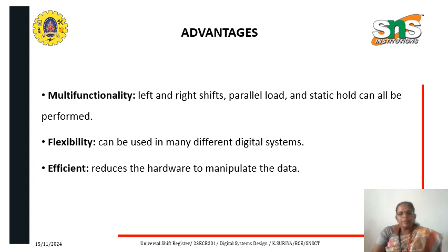Next, we'll see some advantages of universal shift register. It is multifunctional. The left and the right shifts, parallel load and static hold can all be performed in the single universal shift register. Next, it's very flexible. It can be used in many different digital systems. Then it's very efficient, which reduces the hardware needed to manipulate the data.